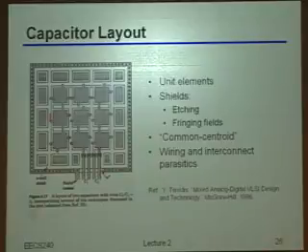Now, if you look carefully at this unit element, you'll see some initially weird looking stuff inside of there. You'll notice they all have these stub thingies hanging off on the sides of the top plates right there. Anybody have an idea why those stubs are there? Yeah. Well, you need to connect the 7 units together, but you don't want to have unbalanced stubs in them.